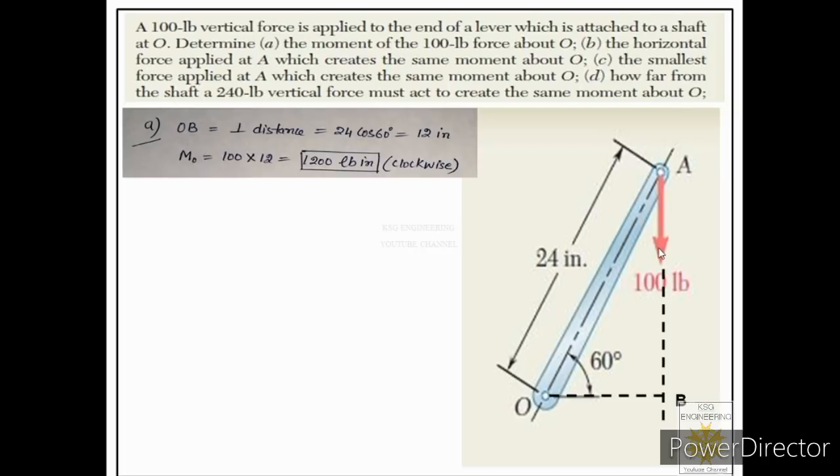Fine. If we draw like this, it will go the other way around. So that is the longest path. Fine. So that will not be considered. The closest path will be, it will try to move towards the moment center. So in that process, the movement it will generate will be clockwise movement. You see, it will try to move towards the moment center. So it will generate clockwise movement. So this way you can judge whether the movement is clockwise or anti-clockwise. But if you consider its longest path, let us say it will move this way around, that cannot happen. So that will be an anti-clockwise movement.